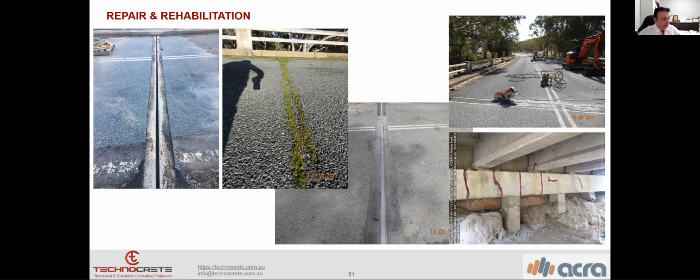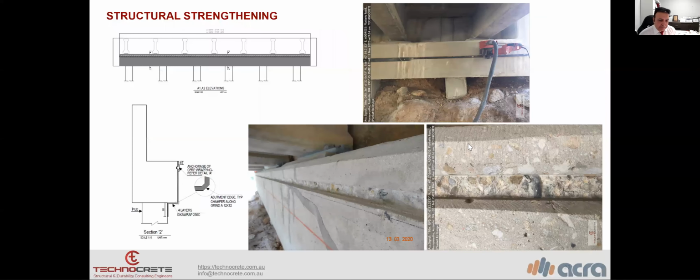Then they had to be repaired properly. You can see on the right-hand side, two left photos. The first one is with the grass. It was the existing expansion joint, and the left-hand side shows the after-repair with the cut, with a specific procedure. Then in the right bottom, you can see the crack repair of the abutment.